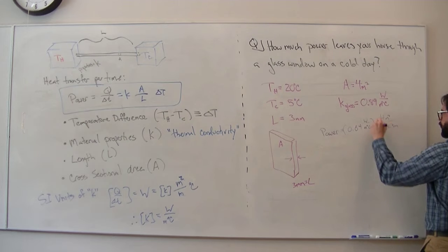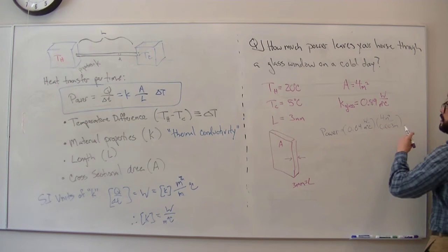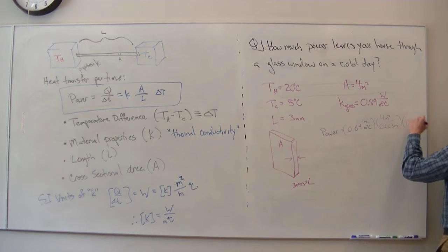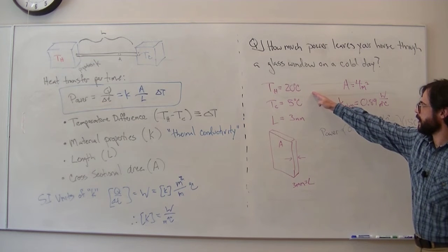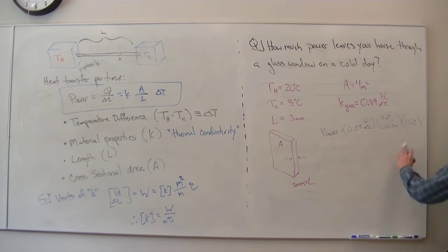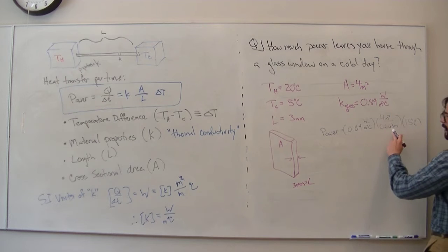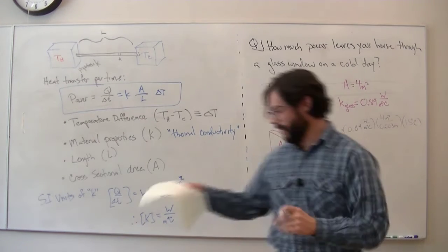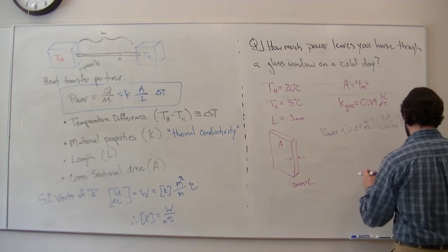And this is where the trouble starts. And then delta T would be 15 degrees, because the interior is 15 degrees Celsius hotter than the exterior. And this term gets pretty big, so you get something like 16 kilowatts, 17 kilowatts, holy heck.